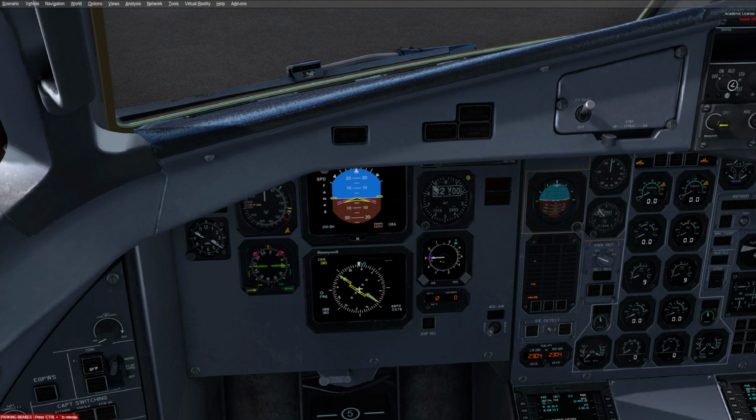The Annunciator Panel is part of your centralized crew alert system. It shows you faults visually. Sometimes it'll sound off an alarm audibly as well. There's 3 buttons at the bottom. Recall to bring back some of the ones that may have been eliminated. This is to clear most of them. And then the takeoff inhibit is here, and that'll eliminate some others and leave others as well.